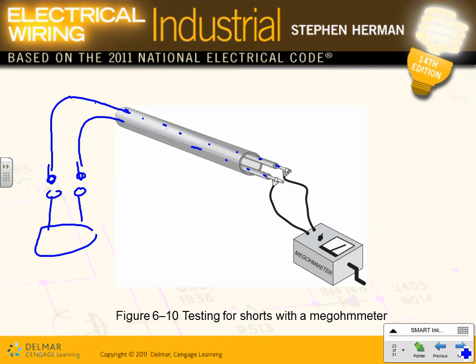If it shows a very high, large value, infinity for example, very high impedance, this means the insulation is good, and there are values for the insulation. Very high value, good insulation. Very low value means you have a short. They are shorted together somewhere here, right? That's basically what they do with insulation. Who cares? It will save you from tripping on a short circuit or ground fault.